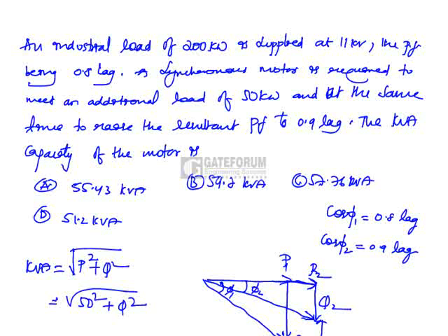Okay, this is the reactive power supplied when the synchronous motor is not connected. Now when the synchronous motor is connected, what is the reactive power Q2 here? Q2 is equal to, since real power is increased by around 50 kilowatt, so 200 plus 50 is 250 into tan phi 2. Okay, now tan phi 2, if you substitute it, you will get around 121.07 kVAr.